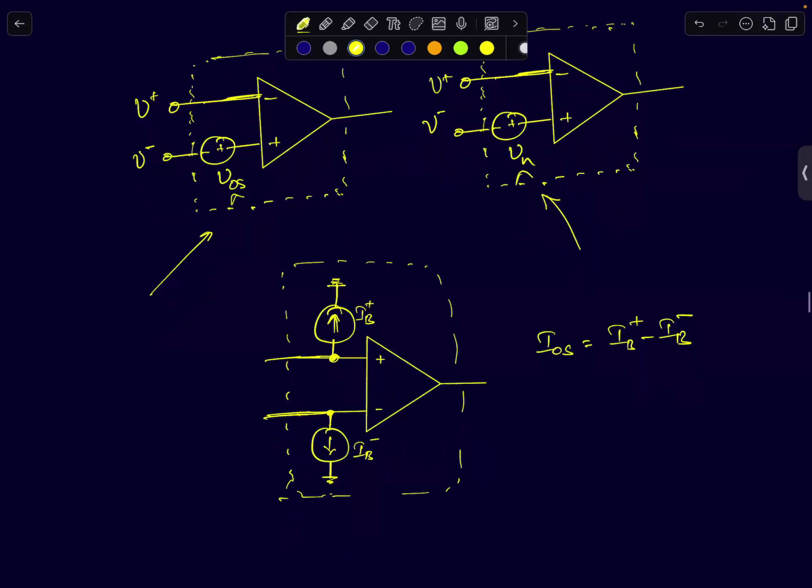And then we discussed another important parameter, which was called the input bias current. And we also defined another parameter called input offset current. If a circuit is purely differential and perfectly matched, then ideally input offset current should be 0. But if the circuit is asymmetric, which will normally be the case due to manufacturing errors, then you will have finite offset currents.